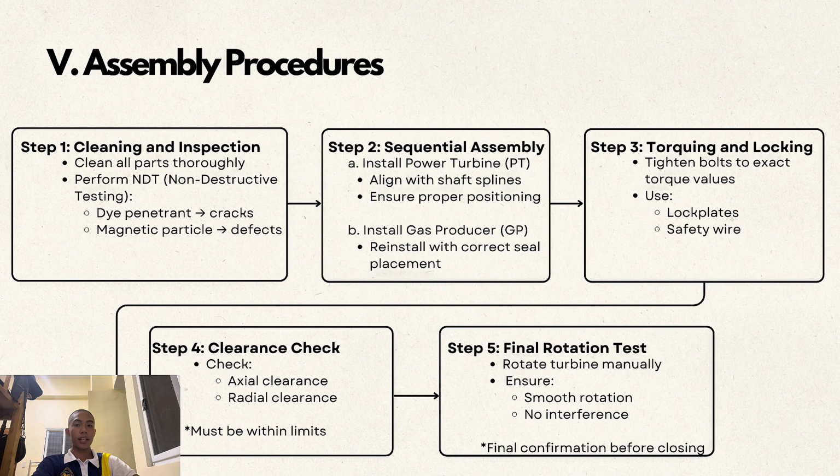Perform a rotational check. Manually rotate the N1 and N2 systems to ensure there is no binding or unusual noise before the engine is sent to the test cell.